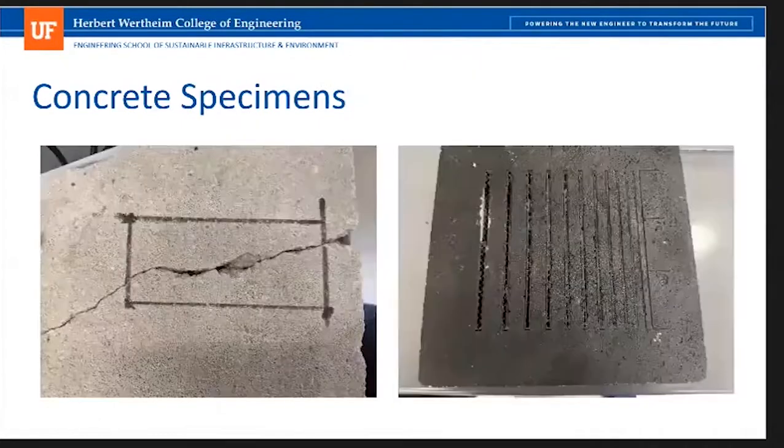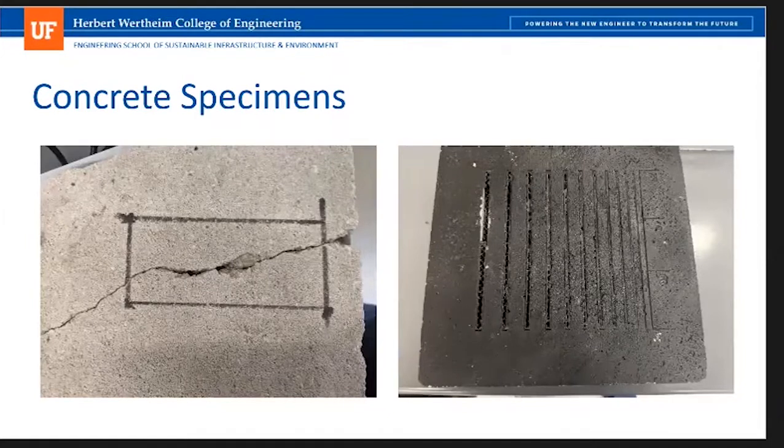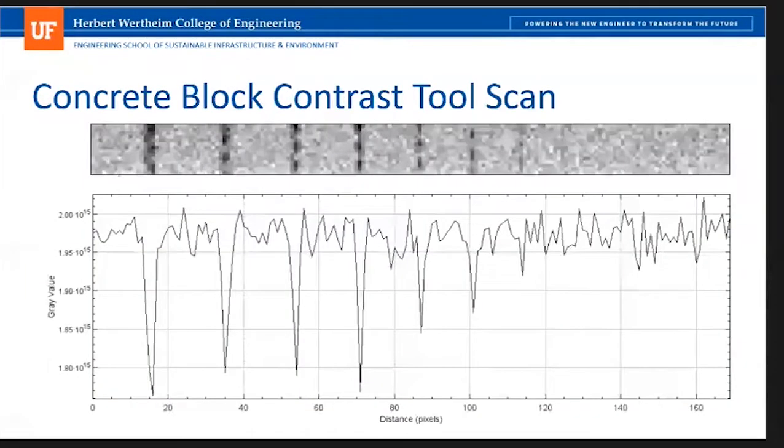So going back to this contrast tool, the far right thickness on that crack would be 1 millimeter. On the left would be 6 millimeters in ½ millimeter increments. So we in the laboratory have been able to estimate and show detection on about the largest 8 of those cracks. So this is in development right now. We're hoping to move into more use of this pretty soon.